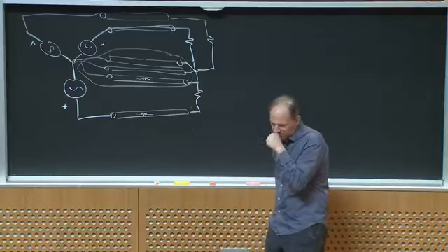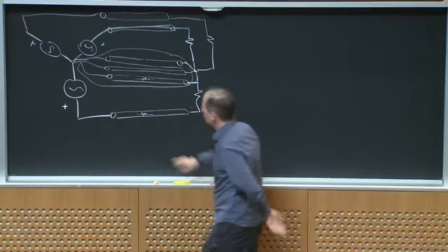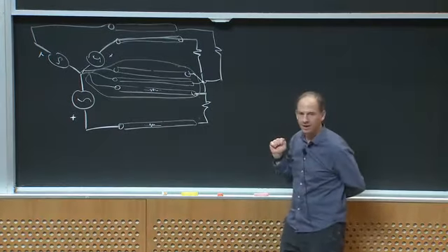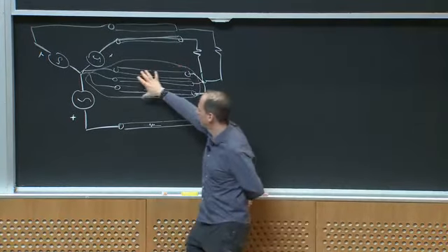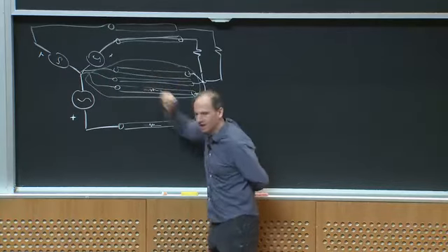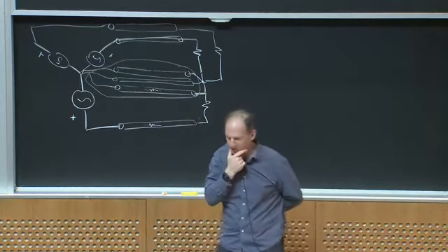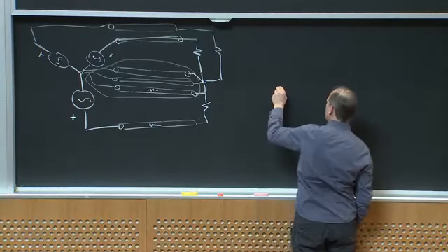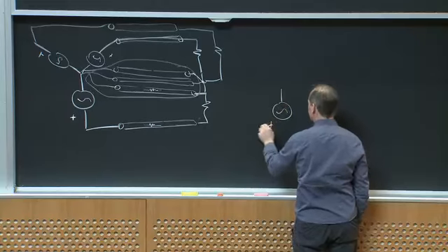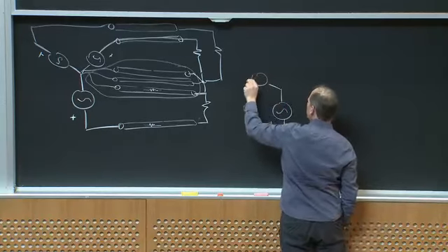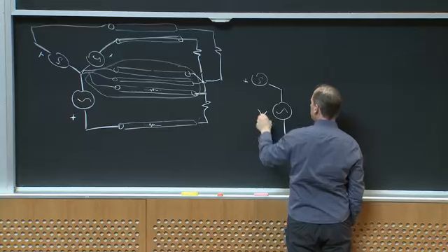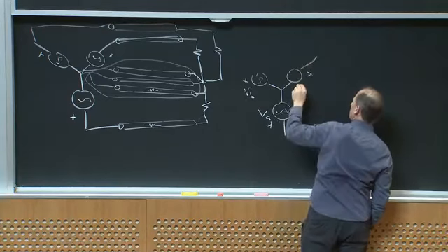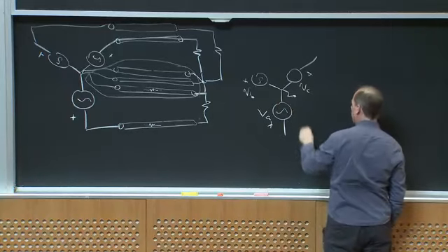What else can we do? Here I showed my source is connected in Y and my load is connected in Y. And that's what lets me throw out a lot of the required heavy copper conductors. But there's nothing that says I couldn't come back here and create a polyphase source like this again. Here's VA, here's VB, and here's VC. And here's my neutral.